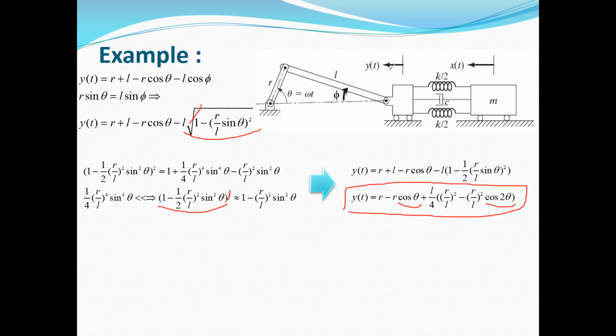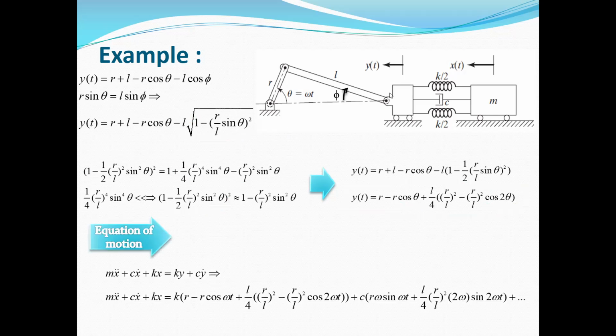Now we can substitute into the equation of motion. When you derive the equation of motion, we can extract the non-homogeneous term for this equation. So if you write the equation of motion for this system, as I told you, this system with degree of freedom xt, and if you, for example, use Newton's second law and plot the free body diagram, when this mass m is going to the left, we will have some forces here, one force due to the spring, one force due to the damper, and all of them will have a negative sign because they are in the negative direction of xt.